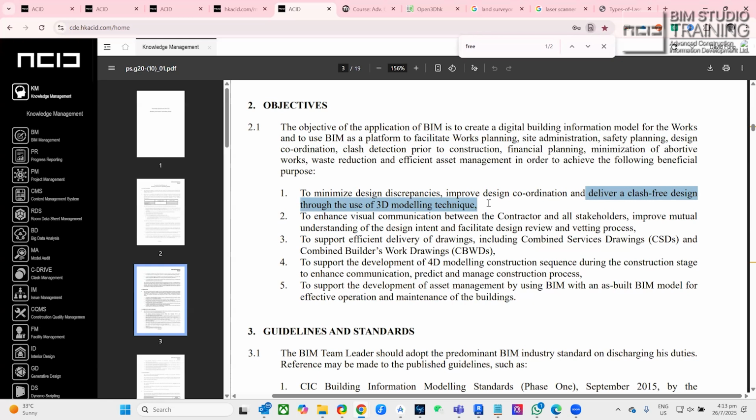So detecting a clash is simple. How much time do you need to resolve one clash? This spec was written in ASD about 4 or 5 years ago. So-called clash-free design doesn't exist. Why? Let me tell you a situation. You have a beam 800 deep. You have a fire pipe 25 mm thick. Do you need to pass through the beam? Is it possible? 800 to 25 mm.